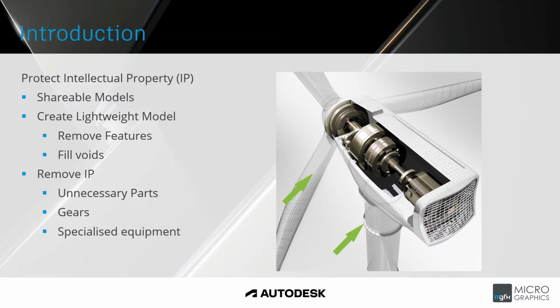We can look at filling voids. If we look at the turbine blade itself, it may be hollow with internal strengthening structures inside of that blade. And you may want to reduce the complexity of the modeling requirements on the PC. So you can fill those voids, make those turbine blades solid. In a way, you're also protecting intellectual property with the types of support structures within the blade.